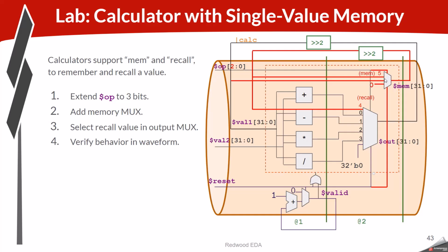Logic synthesis tools can actually optimize away the mux depending on the physical trade-offs. Holding on to state doesn't have to recirculate through a mux. You can often control the clock input to the flip-flop, similar to what we talked about with clock gating.